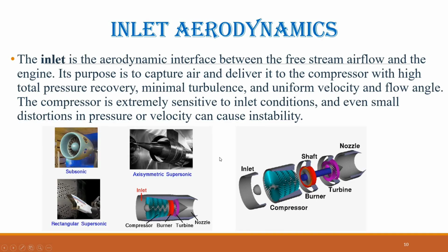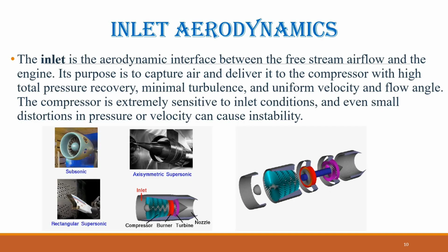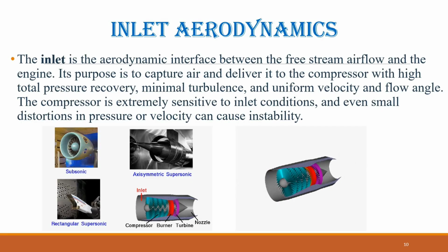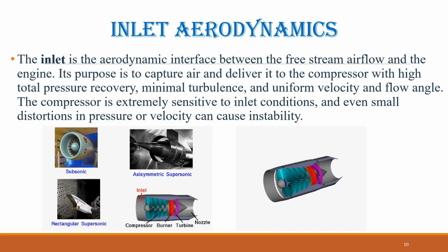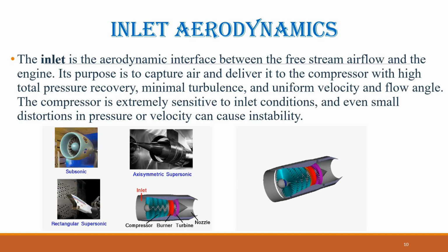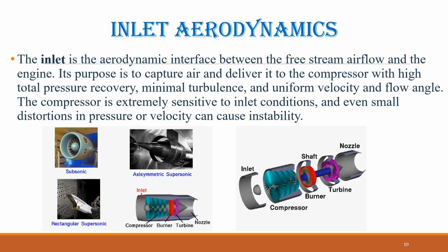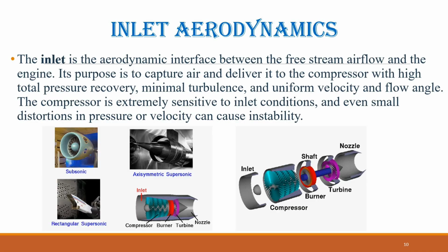A real-world example of advanced inlet aerodynamics is the SR-71 Blackbird. Its variable geometry inlets used precisely controlled shock positioning, and at cruise speeds above Mach 3, the inlet system alone contributed more than half of the aircraft's total thrust by efficiently recovering pressure from the incoming airflow.